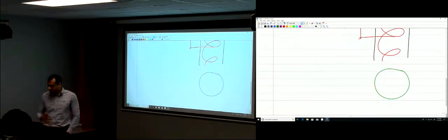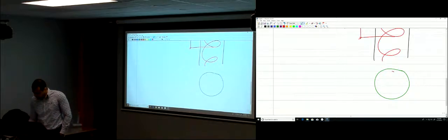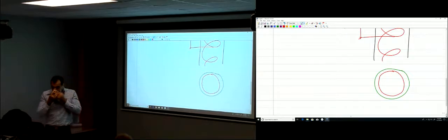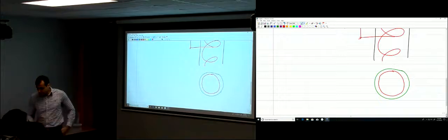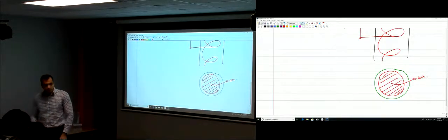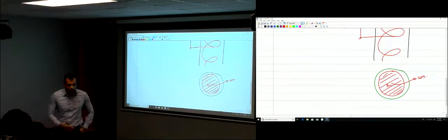That's the outside of the concrete, and then you have your spiral stirrups, and then inside that is the core of the concrete. So I have a cover outside the spiral, and then what's inside is called the core of the concrete. The area of that is AC, the area of the core of the concrete.